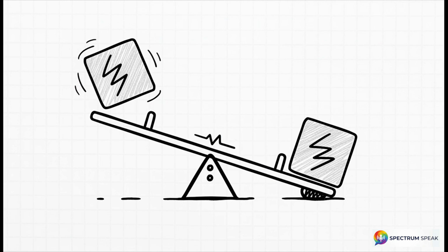To really lock this in, I want you to picture a playground seesaw. The total DC voltage on your network cable, that's the balance of the seesaw. Every positive ternary symbol you send is like dropping a heavy weight on the right side. The seesaw tips. To stop it from slamming into the ground, which means total signal corruption, you eventually have to send a negative symbol to drop a weight on the left side, pushing it back to a perfect 0-volt balance. And the 0 symbols? They don't add any weight at all. Your one job as the sender is to constantly keep that seesaw perfectly balanced.